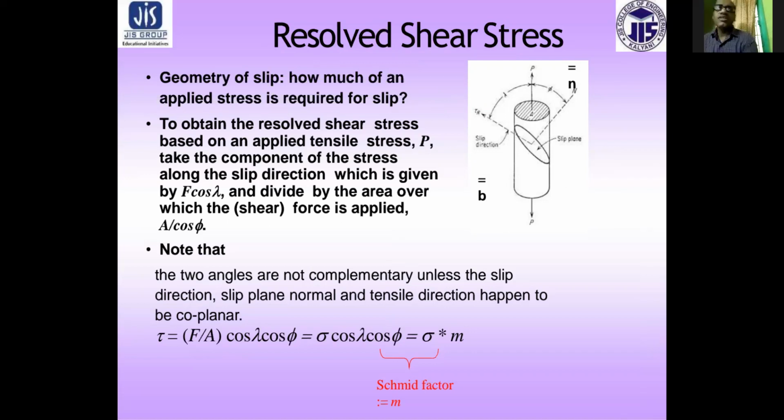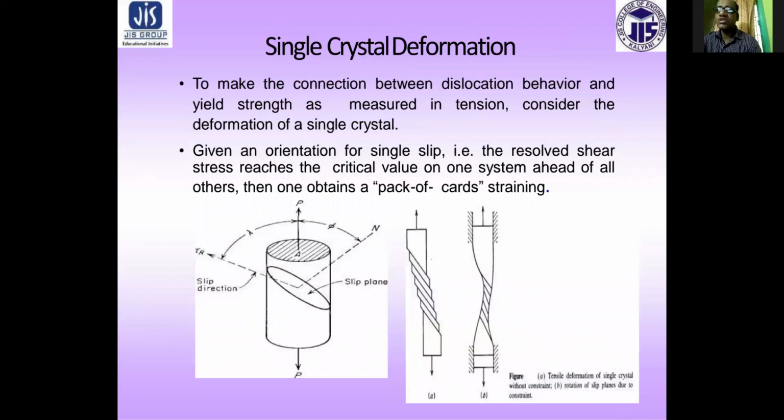Once this is higher than the tau critical, that is, it is higher than the critical stress, plastic deformation starts and can be continued even at lower stress. This phenomenon is called geometric softening. The material becomes soft during plastic deformation. A typical flow curve is shown in the previous slide, actually that is the process of geometric softening in the first figure.